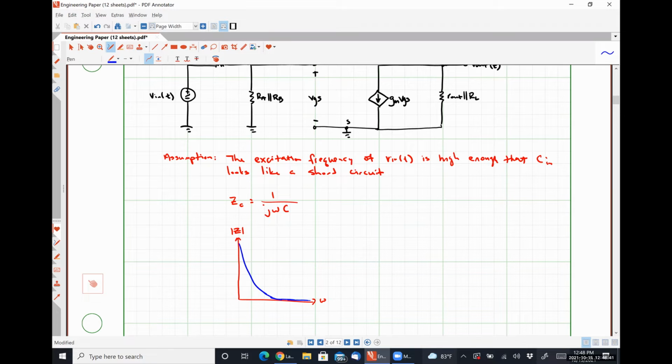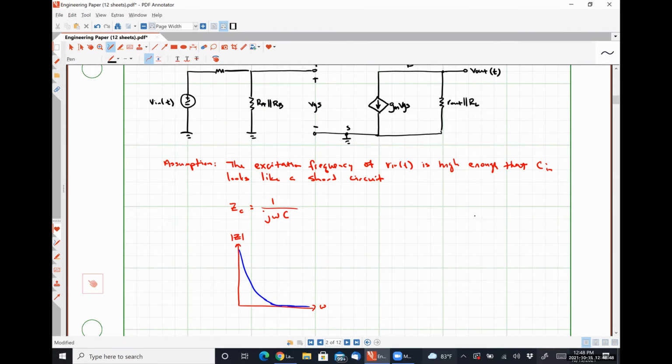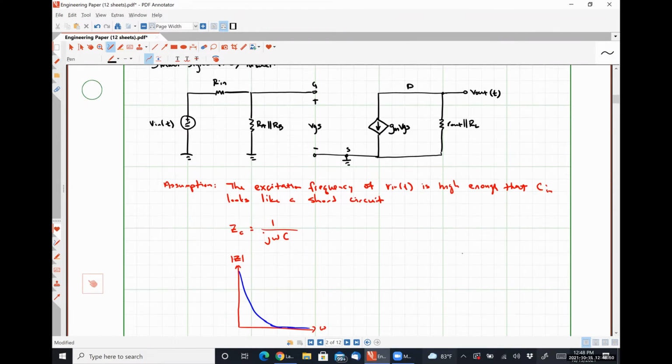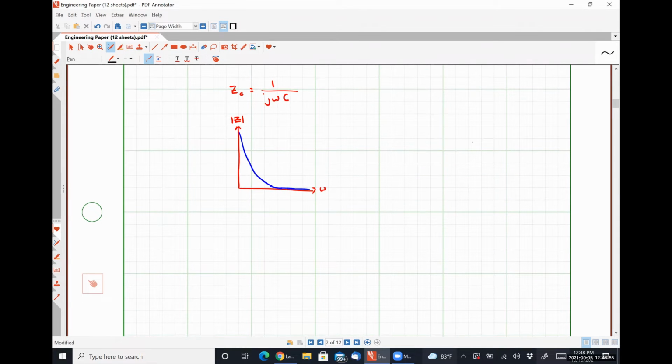All right, so our small signal parameters, gm and rout, are critically important as to how this thing operates as an amplifier. Since we are in the saturation region, we know that gm will be the square root of 2 mu n Cox W over L times ID. And I just want to be clear here, this is our large signal drain current.